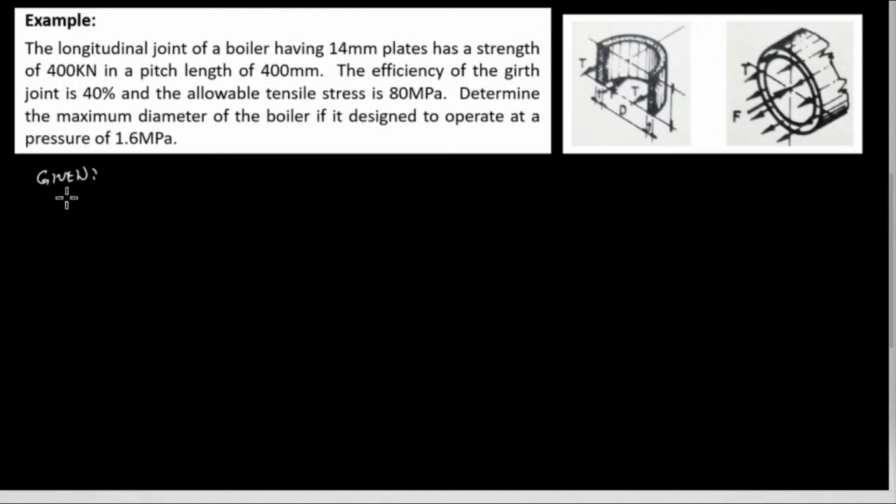are the thickness, which is 14 millimeters, and the tensile force, which is 400 kilonewtons, and the pitch, or the s, is also 400 millimeters. Then the efficiency is 40%, or equivalent to 0.4.